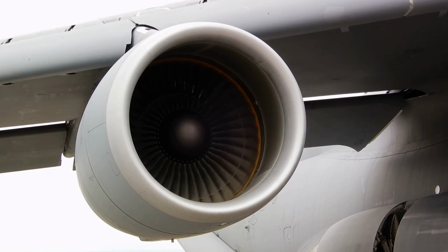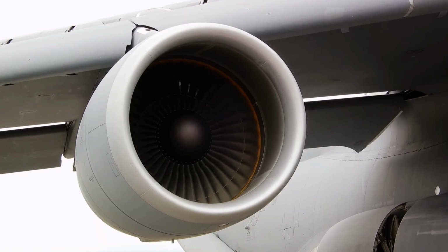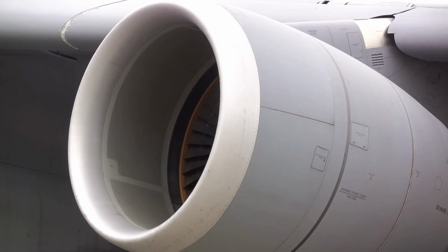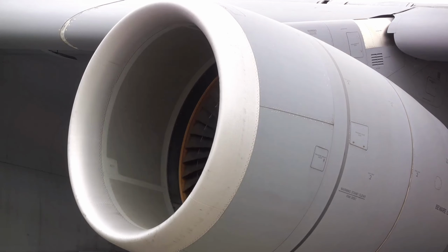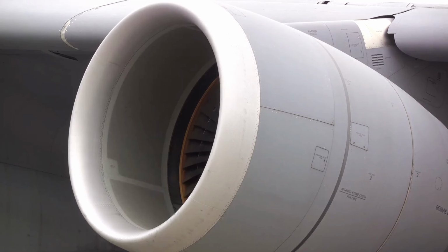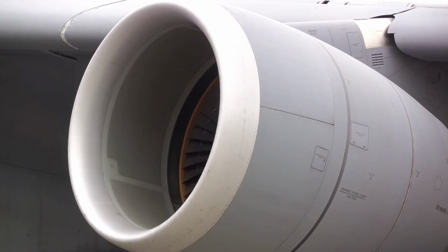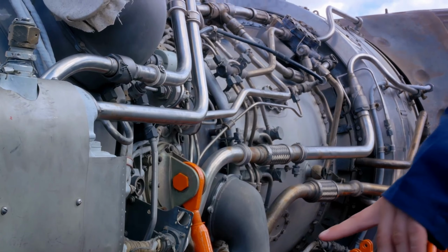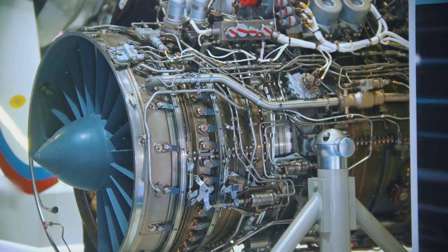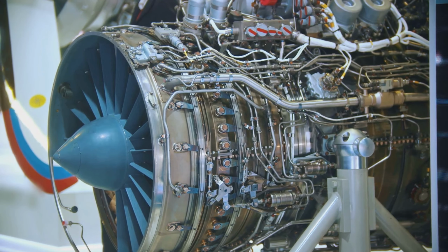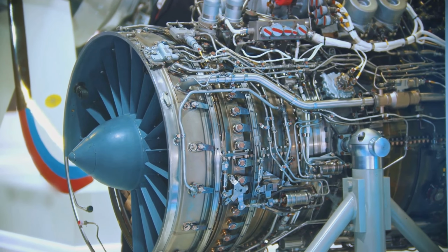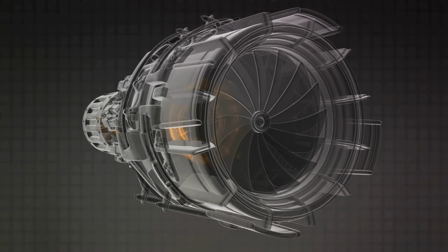On the other hand, the MRF model is used to simulate rotating machinery, such as the turbines and compressors in a jet engine. By defining a rotating reference frame around these components, the MRF model allows engineers to simulate the complex fluid and heat transfer phenomena that occur in these machines, helping to improve their efficiency and reliability.